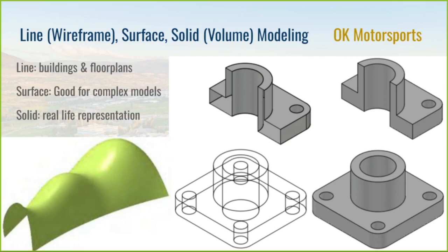So when manufacturing, an example of this, going back to aero, is their toolings. In order to make the shapes that we do, we start off with, I'll just say, a big block of wood, and we carve it down to that shape. Then we take the carbon fiber mat or the carbon fiber sheet, and we just drape it over it, and it assumes that shape. So that is the sheet of carbon fiber that's just rested over this big block of wood.